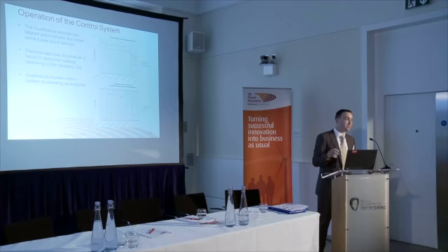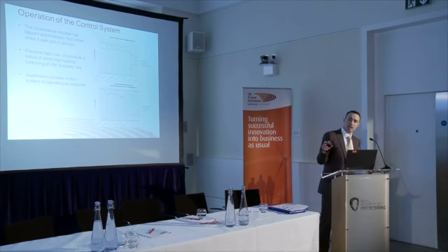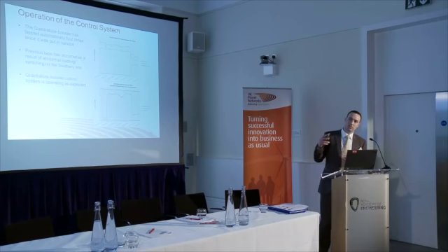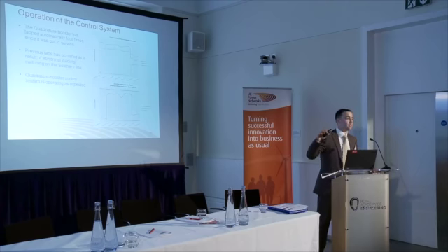I should note that these are 10-minute averaged data, whilst the bottom graph is the deviation between the Downham Market circuit and the Norfolk circuit. The objective of the control system is to ensure that this deviation doesn't exceed the upper and lower bandwidth, which are shown on the bottom graph in the red lines. What you can clearly see from this is that the deviation never exceeds those bandwidths, which is exactly what the control system is trying to achieve.